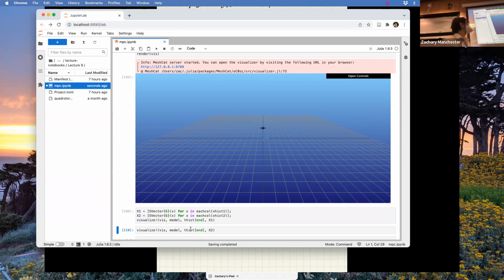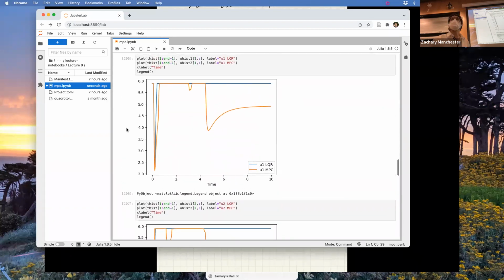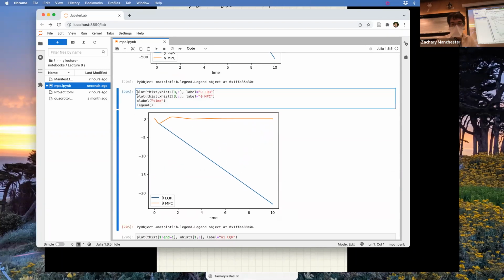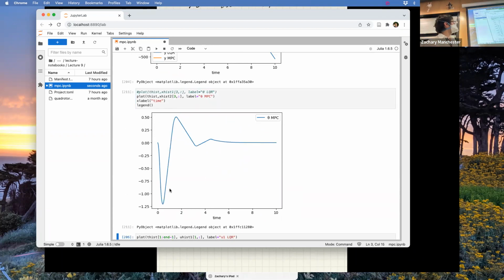There's another thing I can do here, though, that I want to zoom in on real quick that's kind of interesting. Remember we said in the dynamics, the thing we were really approximating with our linearization was the small angle approximation. So let's go look at that. Here's the angle state. I'm going out to like 1.25 radians, so I'm basically sideways at that point. And remember, with that small angle approximation, the reason we're going into the floor is I'm going basically full on sideways, at which point I have no thrust in the vertical direction at all. So I fall. But the linearized model doesn't have that in it, because I made that small angle approximation. So the linearized model still thinks I have vertical thrust when I'm sideways, which is intuitively what's going on here and why that's happening.